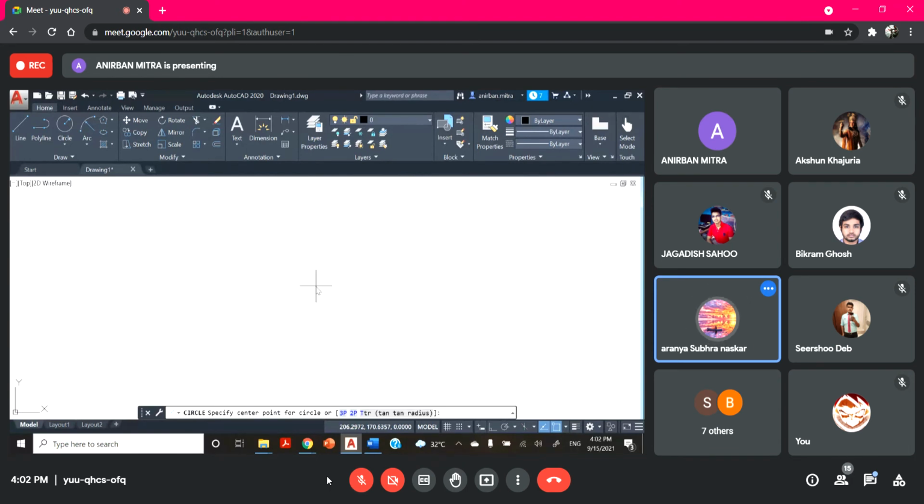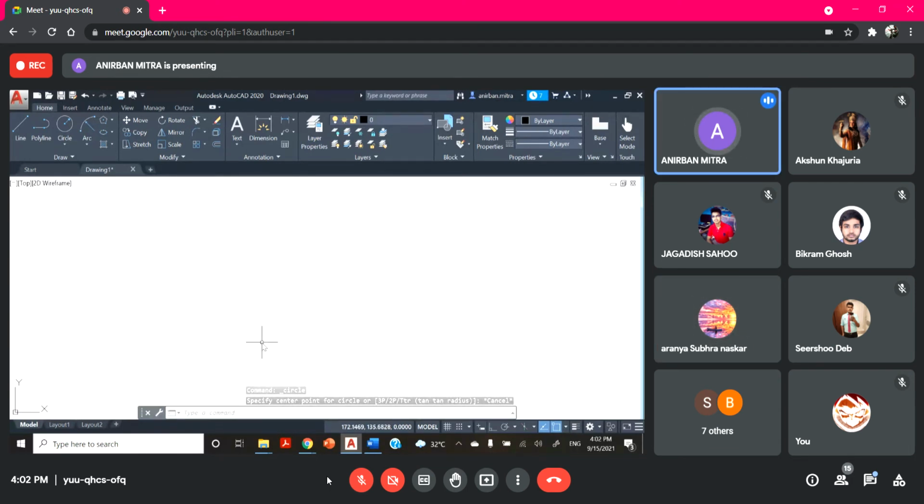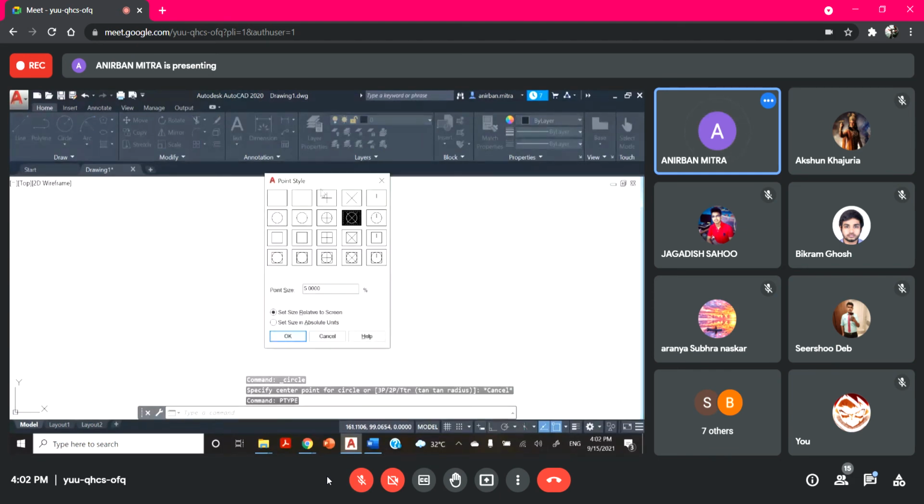P type. PTYPE. I'll do it again. PTYPE. Hit enter. You will get the point style window.